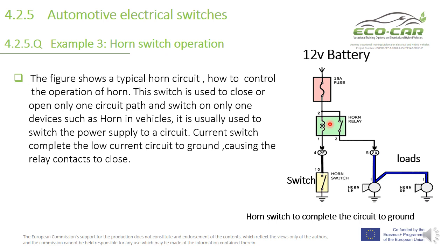This coil is energized when the positive 12 volt is coming to this point of the coil through the fuse, and when the switch is closed, the ground goes to the other part of the coil.